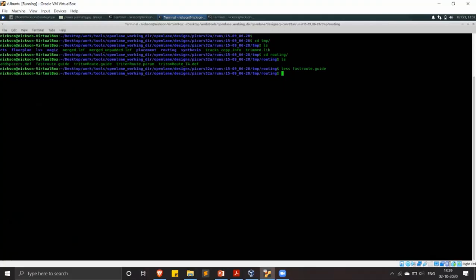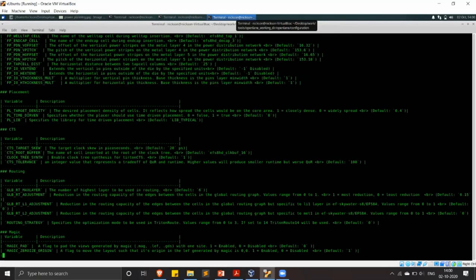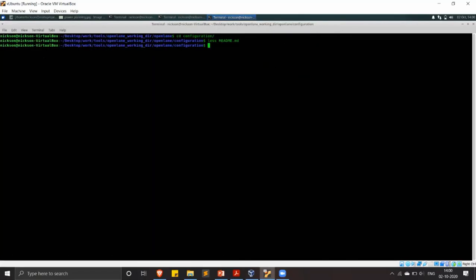The parasitics associated with the routes will come into picture. So the first goal would be to extract the parasitics. In OpenLane till now, the SPEF extractor has not been included, which we have included along with this flow.